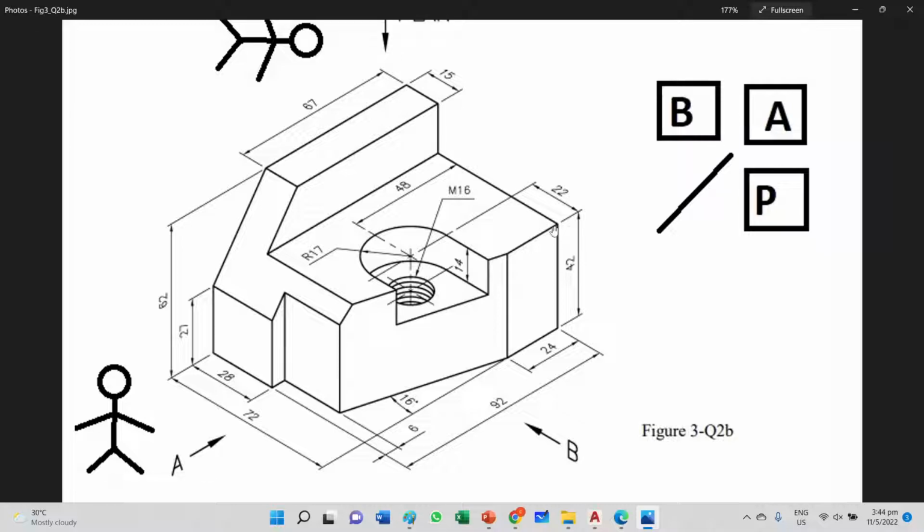I will be looking from right to the left, so I will draw the construction line, and I will create the plan view construction lines. And you'll be looking from the top, and the plan view is drawn vertical below. This is the 45-degree mitre line, and the plan view would have the drawing and I snap it to the extreme of my plan view.